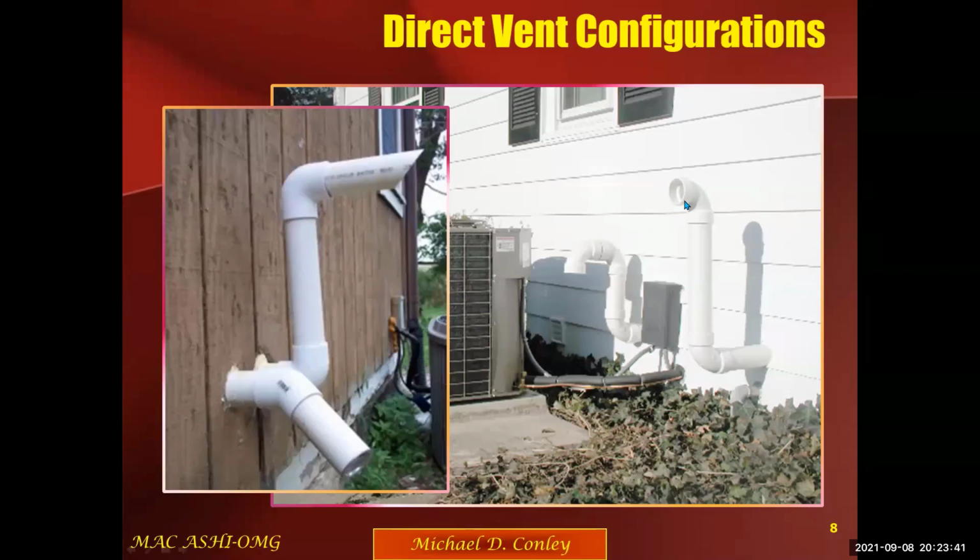This is your exhaust port here. You don't want this exhausting products of combustion being sucked into your AC. I understand. You're talking about it has to be 10 feet from the AC, not the combustion air taken in for the unit. Exactly. And it's not necessarily just the AC, it's any appliance that has the ability to circulate air. Okay. All right. I got you now. That's the difference there. Thanks. You're welcome.